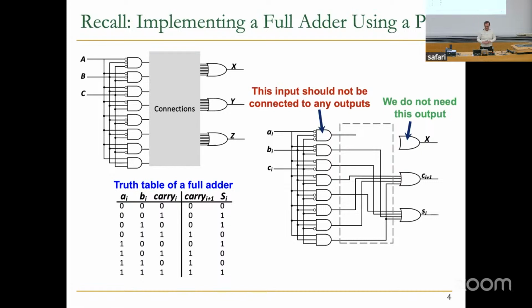So programmable logic array in itself uses a decoder, and you can actually connect the outputs coming out of these gates to the inputs of these OR gates. And this is really the sum of products representation, right? And this was the connection that we built to realize the truth table of full adder using a programmable logic array. I didn't tell you exactly how you would program the connections, and you don't need to know that, except for connecting these outputs of the AND gates to the inputs of the OR gates over here. But there may be many ways of doing that. That's beyond the topic of this course. But essentially, a programmable logic array enables a sum of products representation in a programmable way.